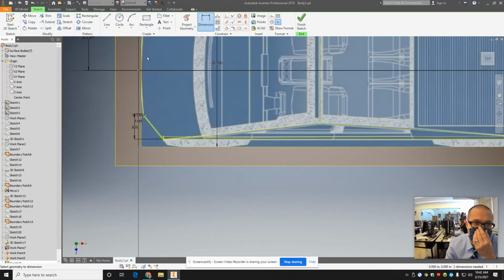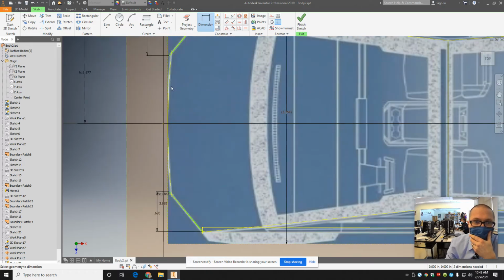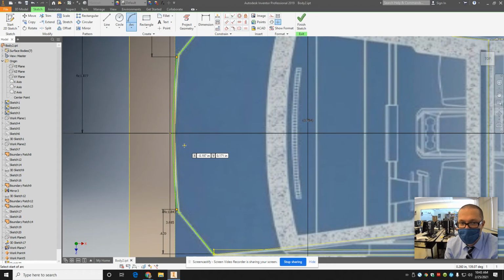All right, so now we know that's symmetric. And the final thing is to put an arc from the two endpoints. And now, remember I said I'm just going to split the difference between the front of the windshield and that vertical axis in this view I'm in. It should basically run now parallel to the other one approximately. And you don't need the geometry projected.